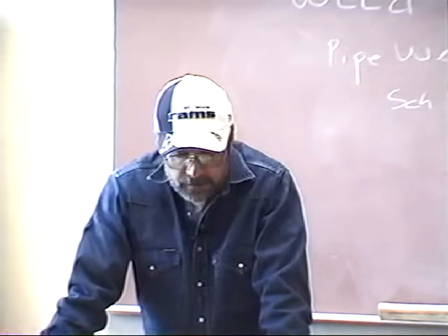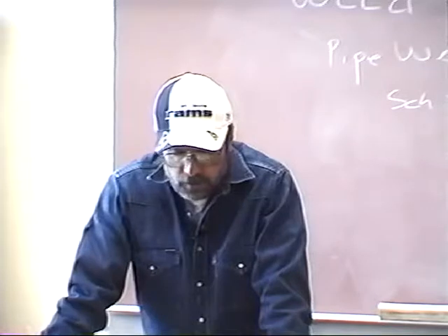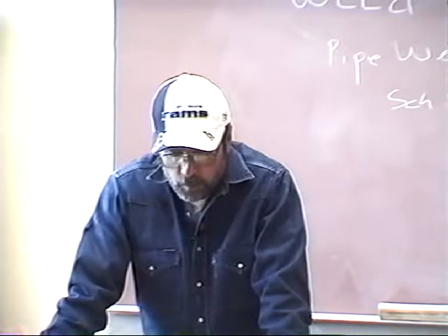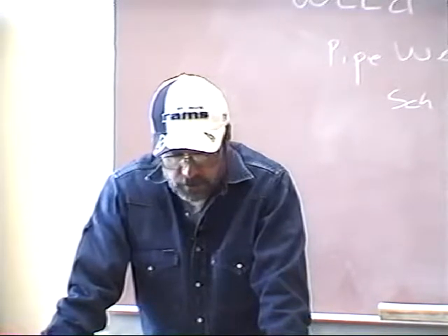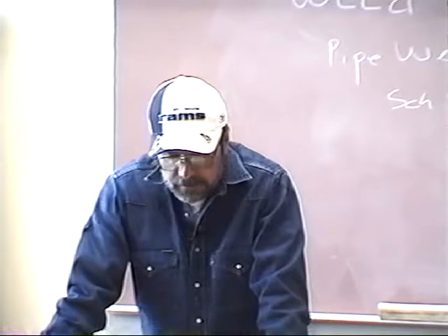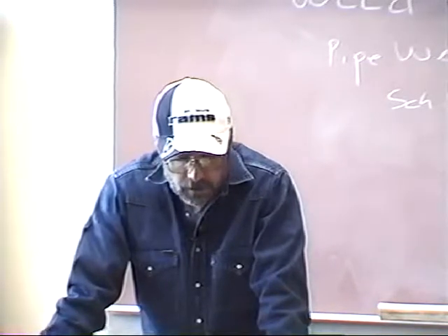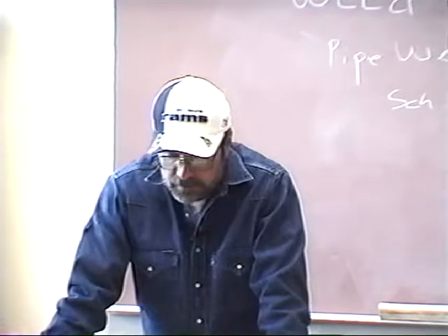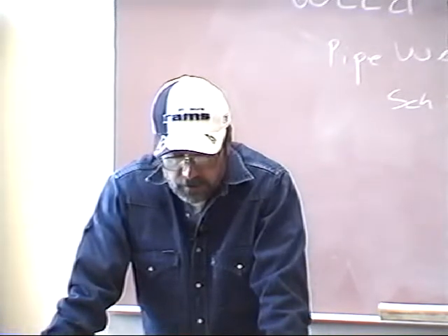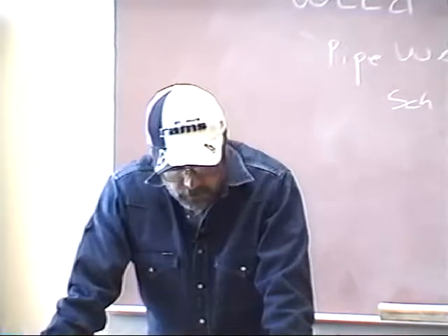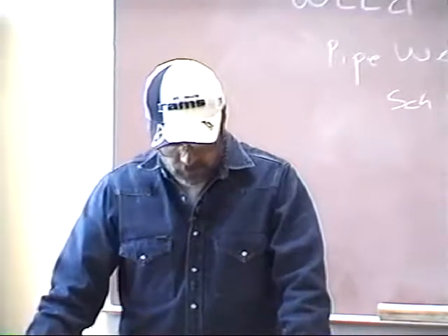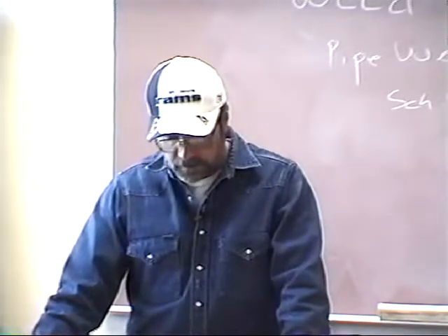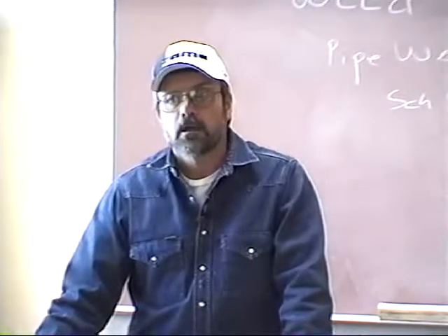When welding, the heat input into the puddle is often controlled by the welding speed and by the weave or whip, as discussed further on in this book. However, more correctly, this is a matter of heat distribution. Unfortunately, it is not possible to provide exact recommendations for the current settings to be used in each case for the following reasons. Number one, the adjusting devices on all welding machines are not the same. One machine set at 90 amps may liberate the same amount of heat as another machine set at 130 amps.